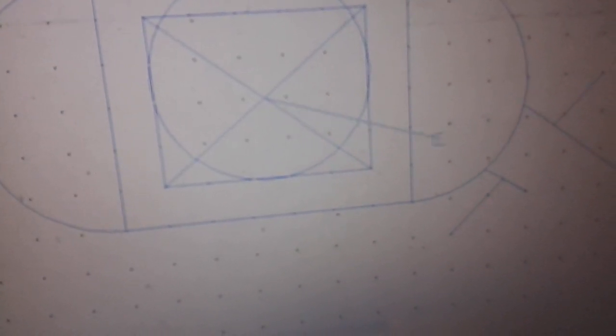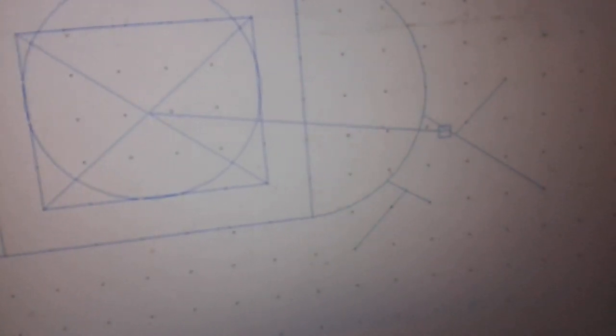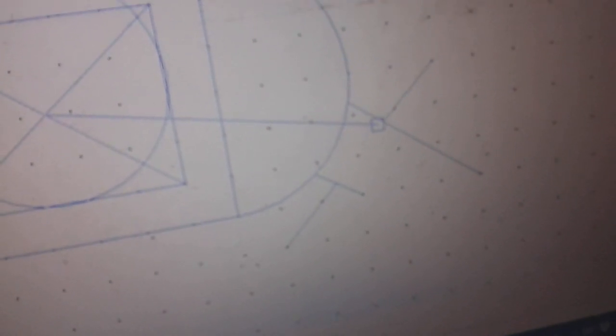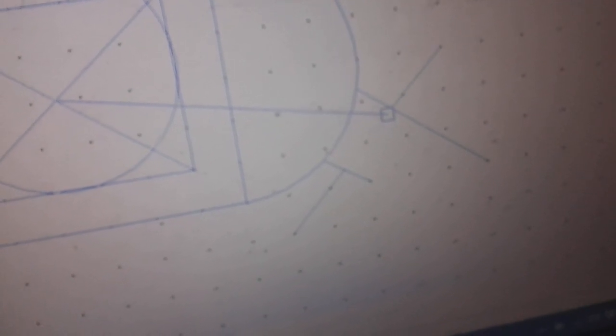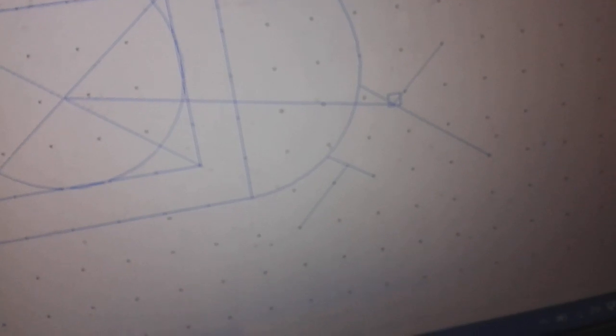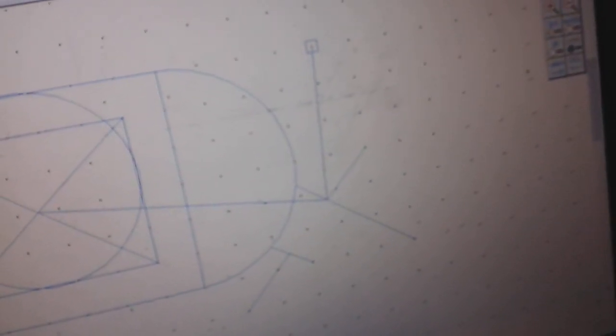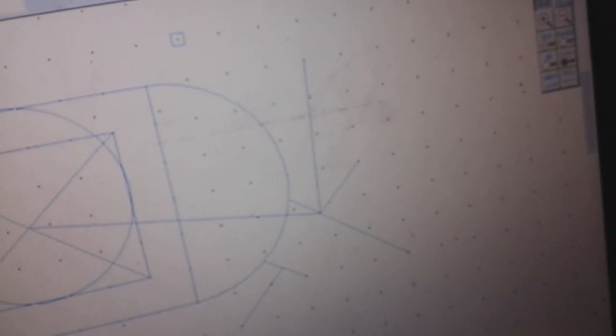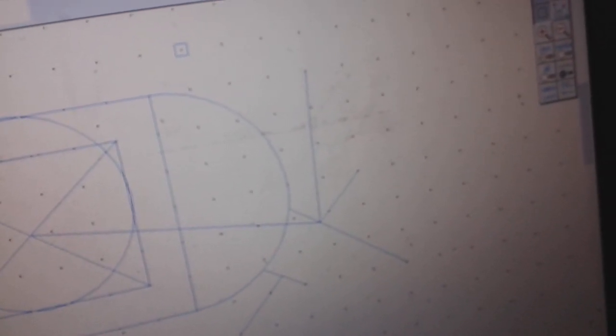If I then want to draw a line to this intersection here, I do exactly the same. I get the square box to be directly over that intersection before I press the left-hand mouse. If I want to draw from there to the grid again, I click over there with my left-hand mouse. I can then go over here and turn my grid back on. So I'm now snapping back to the grid, and then I can go up to my grid point like there, and I can snap on and it will snap back to my grid.